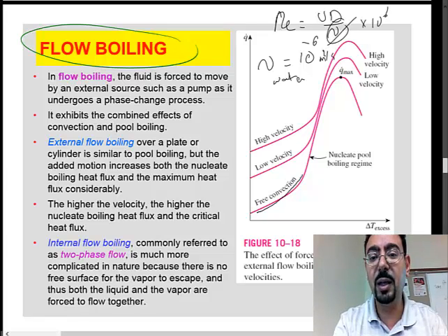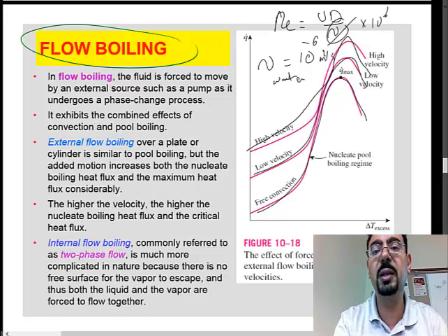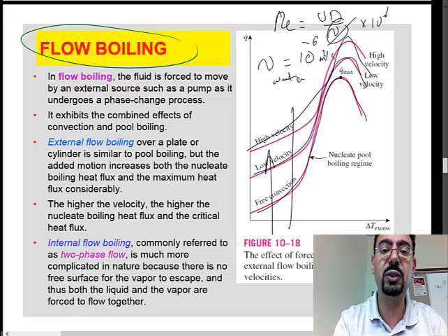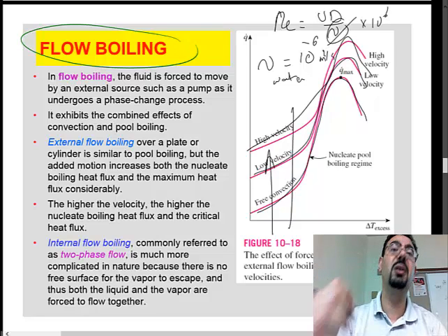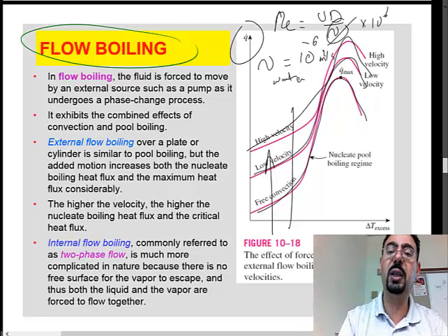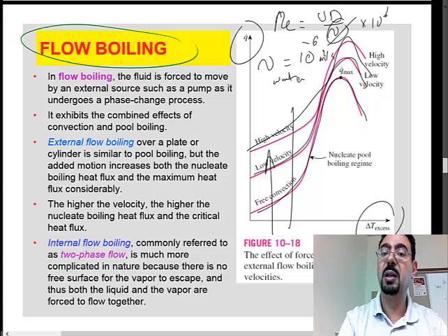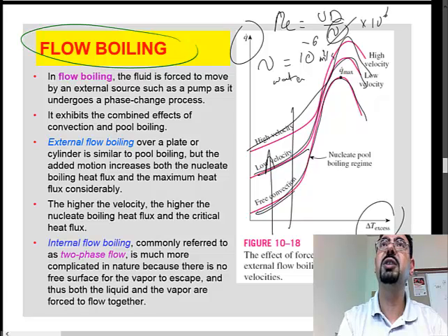This is the nucleate boiling without any flow, and once you increase the flow velocity, it goes like this and goes like this. So those are the convections. Of course, the convection gets stronger and stronger. Again, we're looking at the Q against the delta T. So of course, the pure convection, natural and forced convection, is much higher. Remember, this was a log scale. That chart was log scale. So it's not like twice as much. That's like 10 times as much. This is 100 times as much.